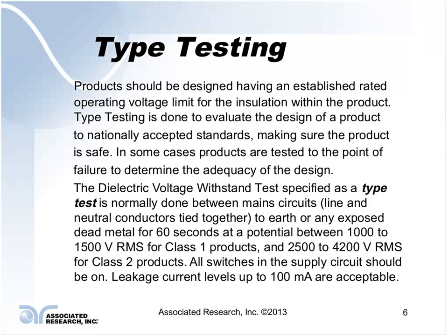If we keep that in mind about the Hipot test, I think it sheds a little bit more light on why this test is actually being performed. But anyway, let's talk a little bit about a type test. When a product is designed, it should be designed having some established limits, operating voltages for the insulation within the product, the conditions that it's going to be used under, what kind of pollution degree, this kind of stuff.